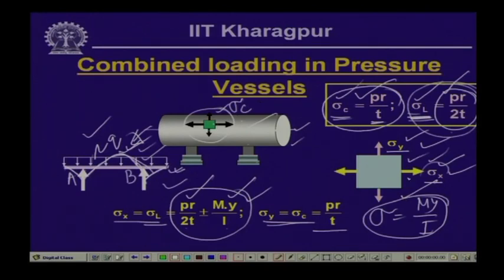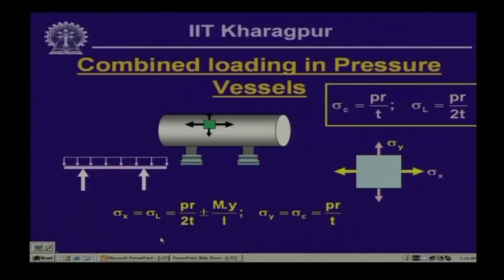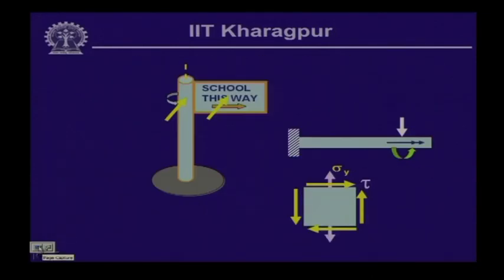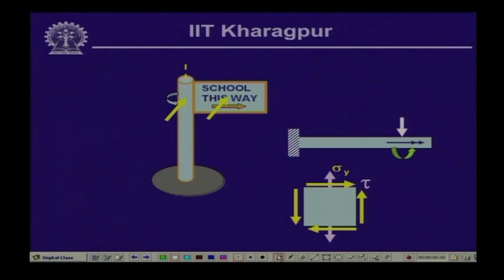Well, the third question was: on a road sign which we normally use, what kind of stresses will the wind load induce in the vertical member? As you have seen, the road sign which is projecting from a vertical shaft is subjected to the wind force when the wind acts normal to this particular plate, and the force will be acting through the center of gravity of the plate. If we call this load P, and we transfer it to the vertical shaft member, it will be transmitted with a twisting moment T.